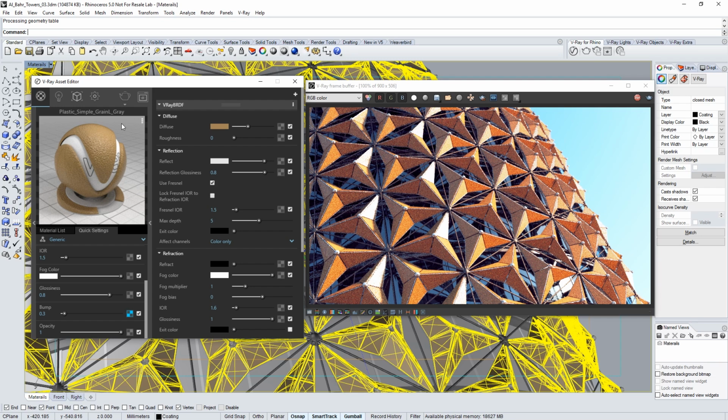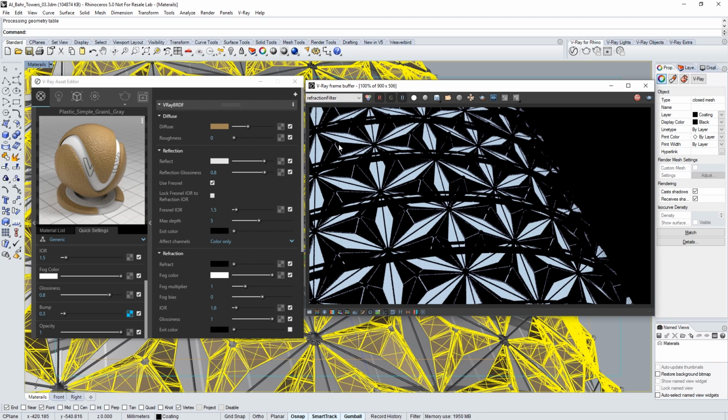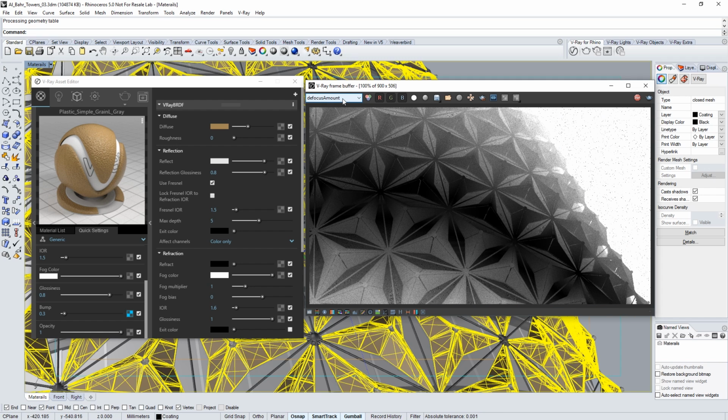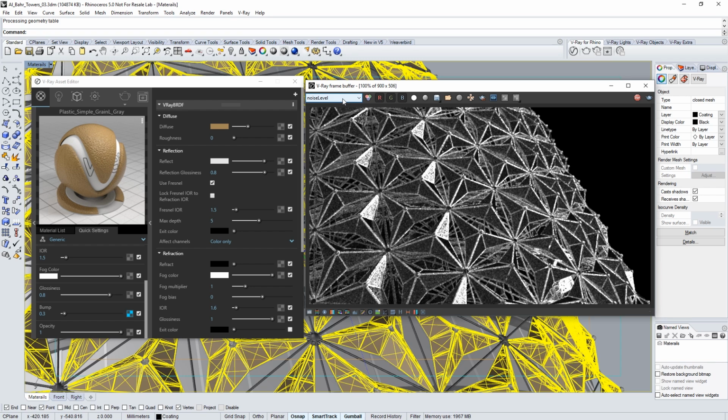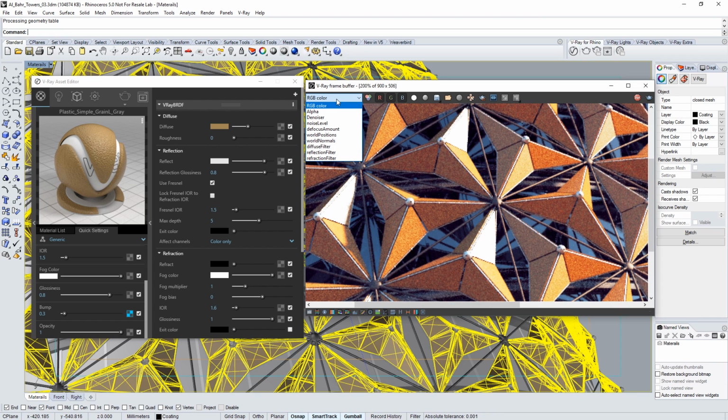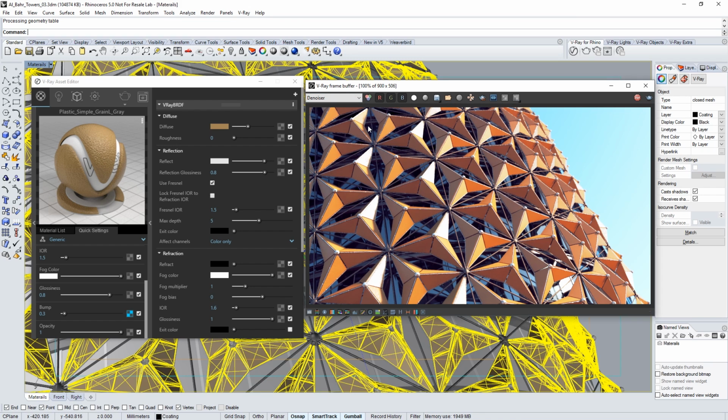But when you get a perfect quality of your image, the denoiser take information from different render elements: refraction filter, reflection filter, diffuse color, world normals, position, the focus amount, because in our image we have depth of field effect, and noise level. Here you can see the denoised result, and from this here we can produce right here this denoised image. Again, with time and feeding the denoiser with lot information, we can get a perfect result in less time.